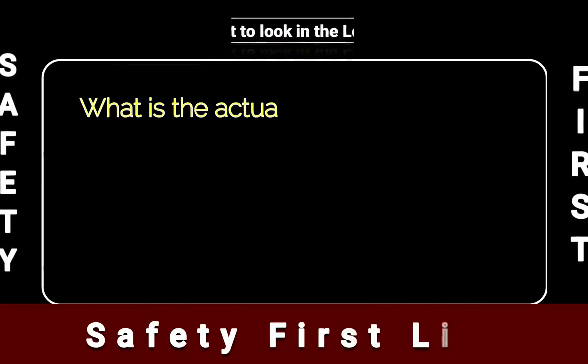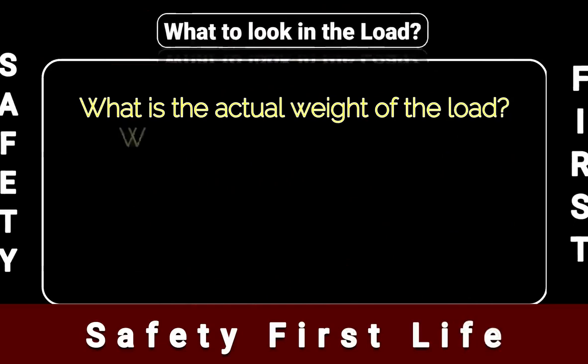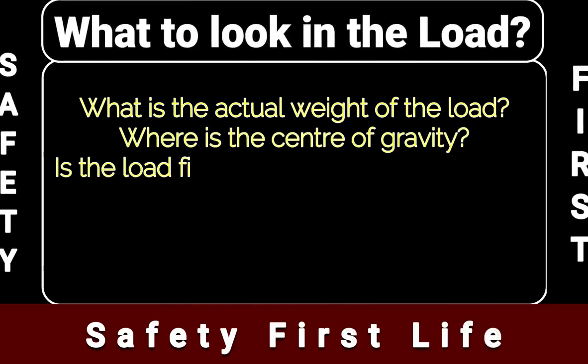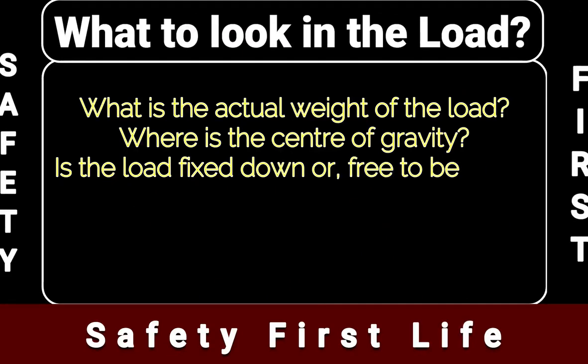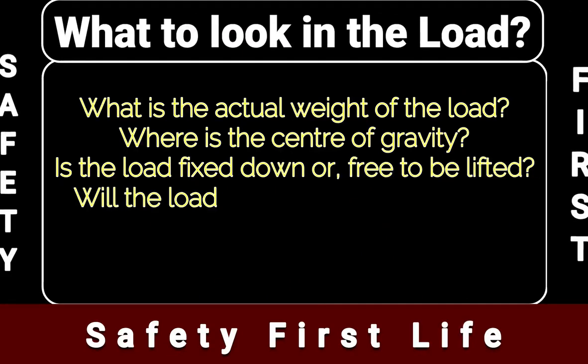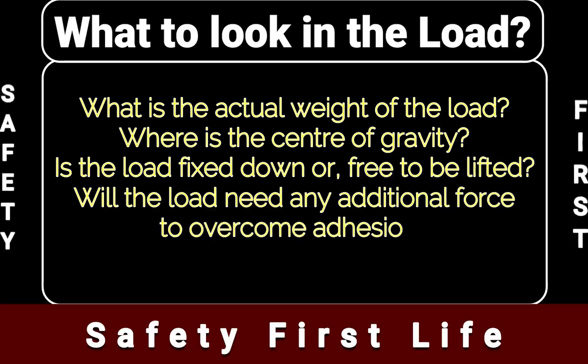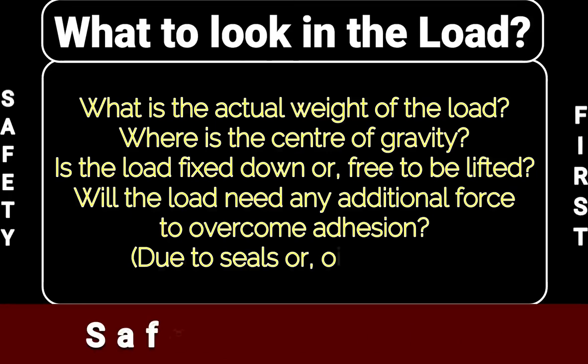What is the actual weight of the load? What is the center of gravity? Is the load fixed down or free to be lifted? Will the load need any additional force to overcome adhesion due to seals or oil, grease, etc.?